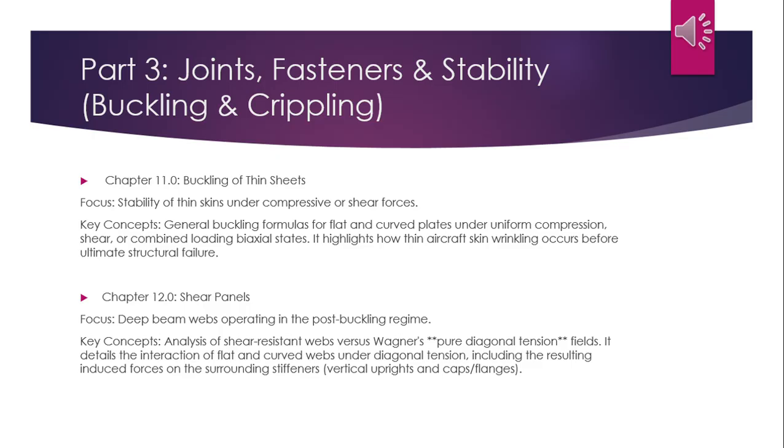Buckling of thin sheets focuses about stability of thin skins under compressive or shear forces. The key concept is general buckling formulas for flat and curved plates under uniform compression, shear, or combined loading, biaxial states. It highlights how thin aircraft skin wrinkling occurs before ultimate structural failure.